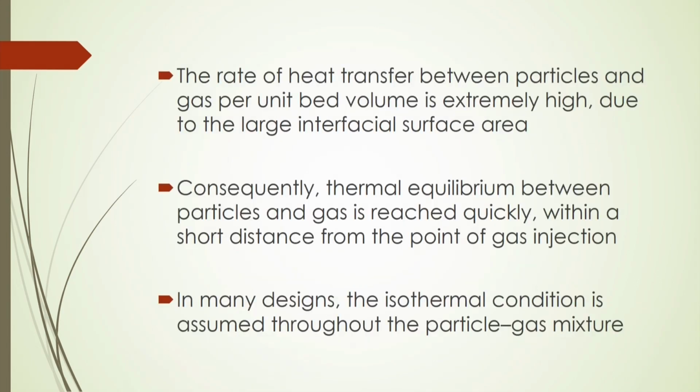Now, the rate of heat transfer between the particle and gas per unit bed volume is extremely high, due to the large interfacial surface area. If we decrease the size of the particles, you will see that more surface area of the particles will be inside the bed, because of which you will get more surface area for transferring heat from the particles to the medium.